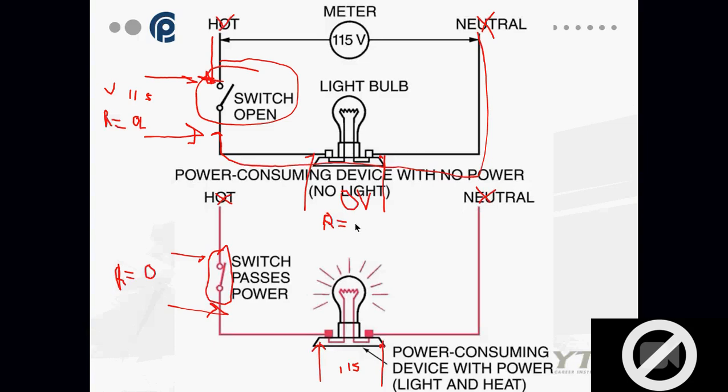What if I have an OL from here to here? What if my meter reads OL? What can you tell me about the load? Could be 2 problems. It could be either something wrong with the load or a wire before it. It's either going to be in the connection or something's wrong with the load. So you pull the bulb out and just ohm the bulb out. Okay.